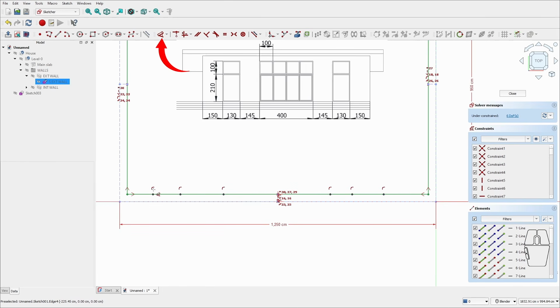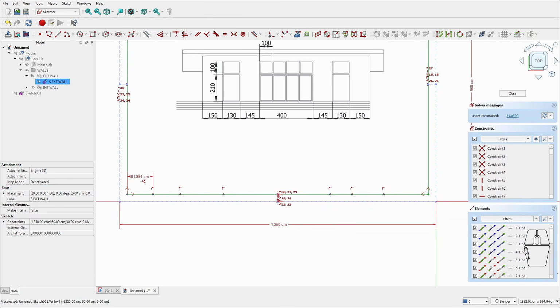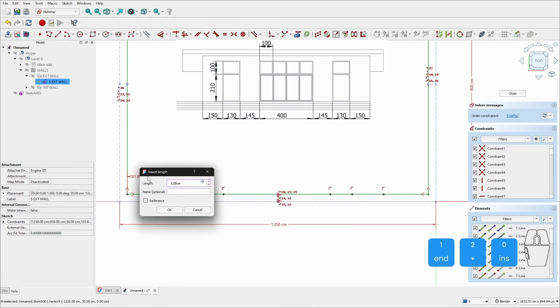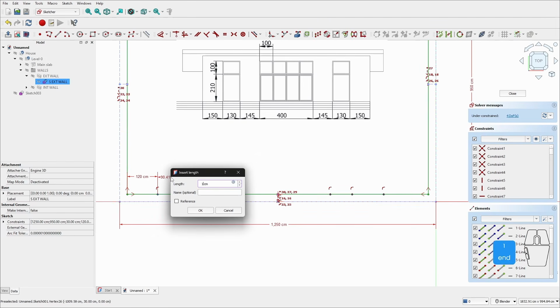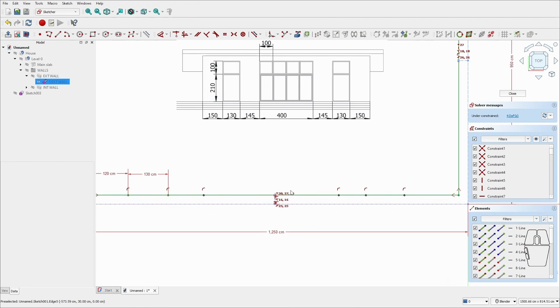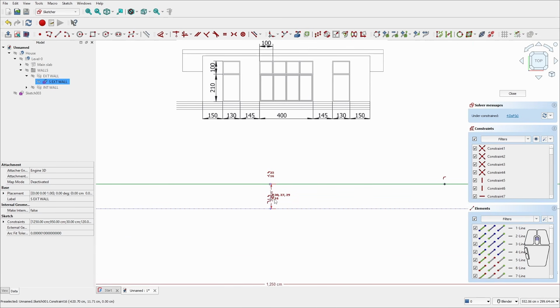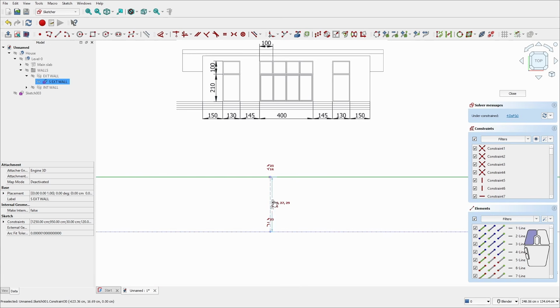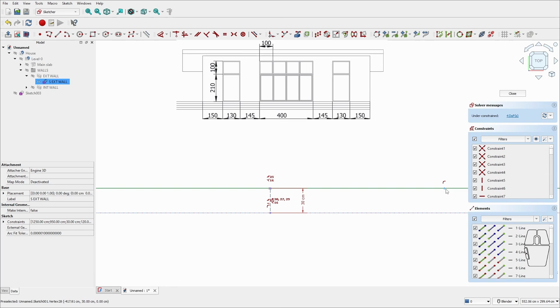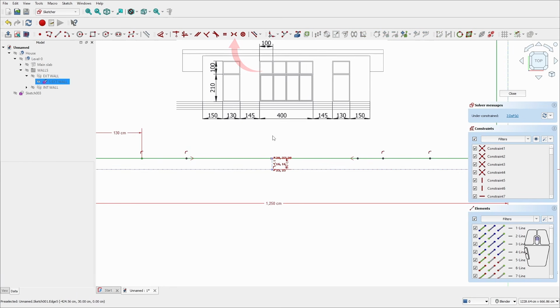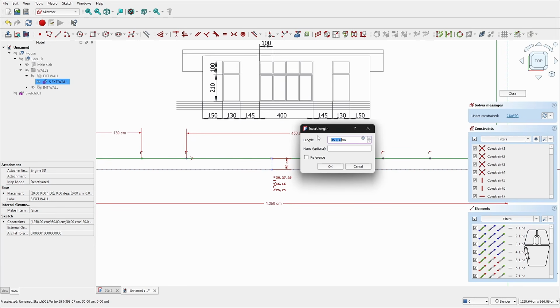Once the points are placed, utilize the dimensioning tools to establish dimensions as shown in the drawing. Remember that the wall thickness is 30 centimeters, so you'll need to subtract 30 centimeters from the overall dimensions at the beginning and end of each wall edge. To center the large window, select one endpoint, then the blue axis, followed by the other endpoint. Apply a symmetrical constraint using the corresponding icon. Using the dimensioning tools, determine the remaining missing dimensions.